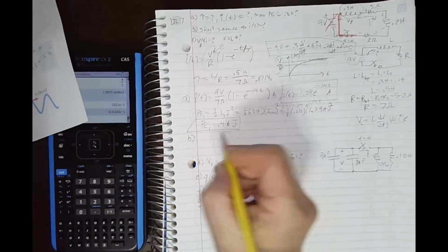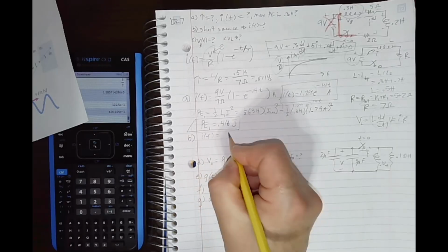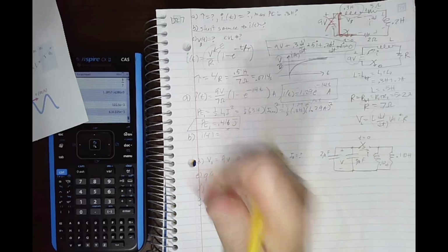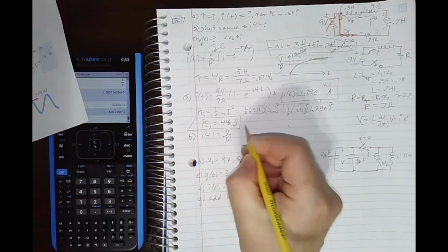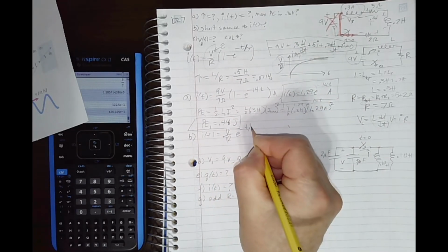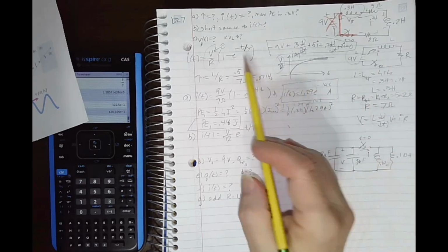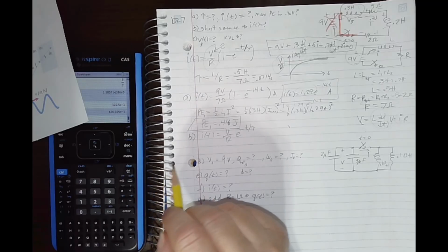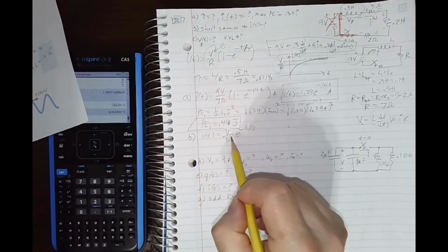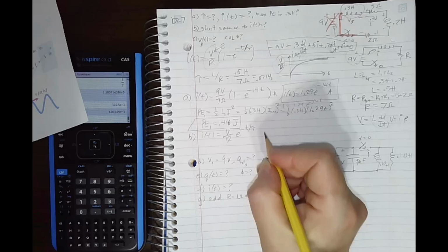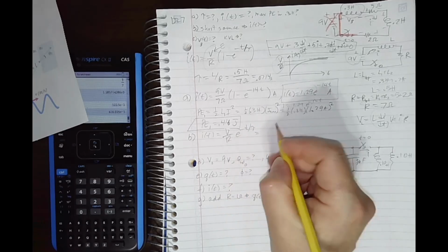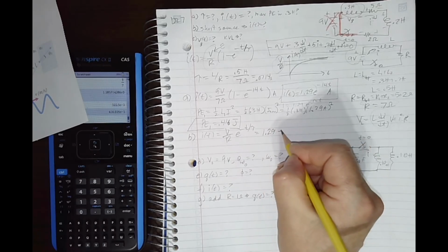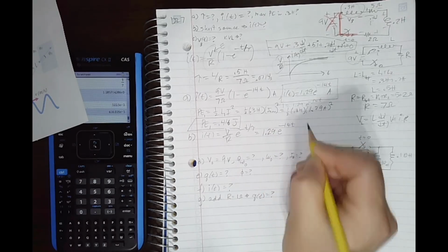All right, so we're going to use I of t is just the same I max, E over R, V over R, e to negative t over tau. It's the same circuit, so it's got the same tau, so it's still 0.0714, or when we take 1 over tau, because it's t over tau, we get 14. And the maximum current is still the same, 1.29 e to the negative 14t now.